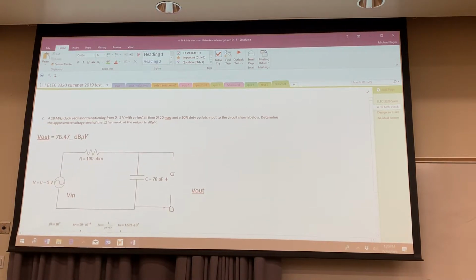So, in this case, when we do the typical sketch here, this is 20 times the log of 2 times the magnitude A times the duty cycle. Well, the duty cycle is 50%, so that and the 2 cancel and you get A, just the magnitude. It's divided by 10 to the minus 6 because it's going to be in dB microvolts.